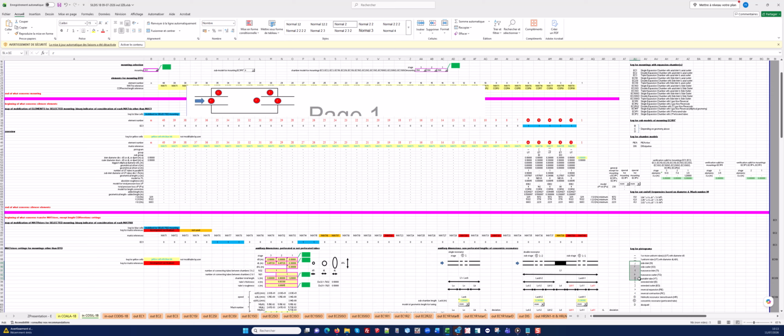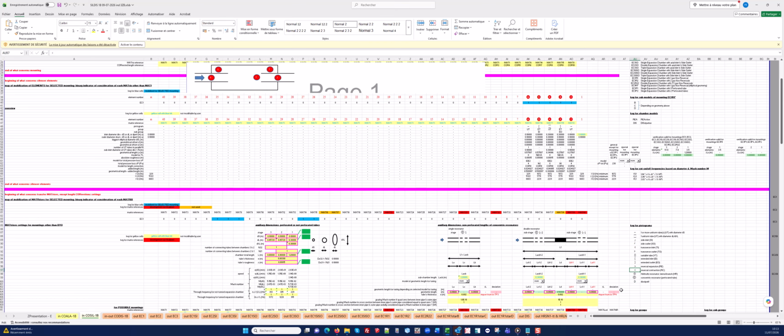Could be also, depending on the case, a side inlet, a side outlet, a transverse inlet, a transverse outlet, or a variable tube in case of elliptical geometry. Could be also a reversal expansion or a reversal contraction in case of overlapping tubes. Could be a Helmholtz resonator with a lateral branch, and could be also a concentric resonator with perforated tubes.